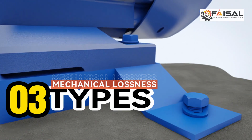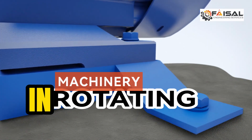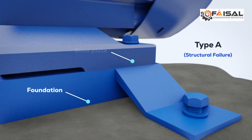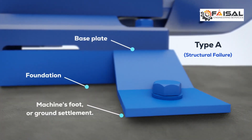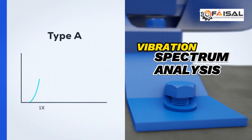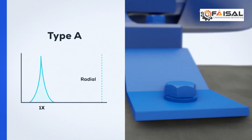There are three types of mechanical looseness in rotating machinery. Type A looseness is related to a lack of sturdiness in the foundation, base plate, machine's foot, or some ground settlement. Via spectral analysis, it's possible to identify this condition by a vibration peak in the first harmonic.